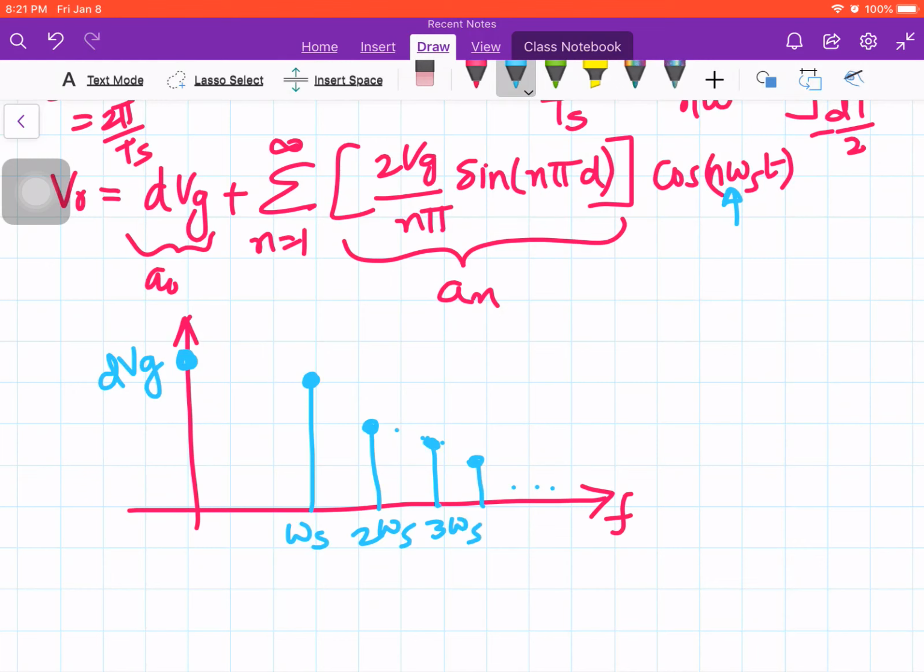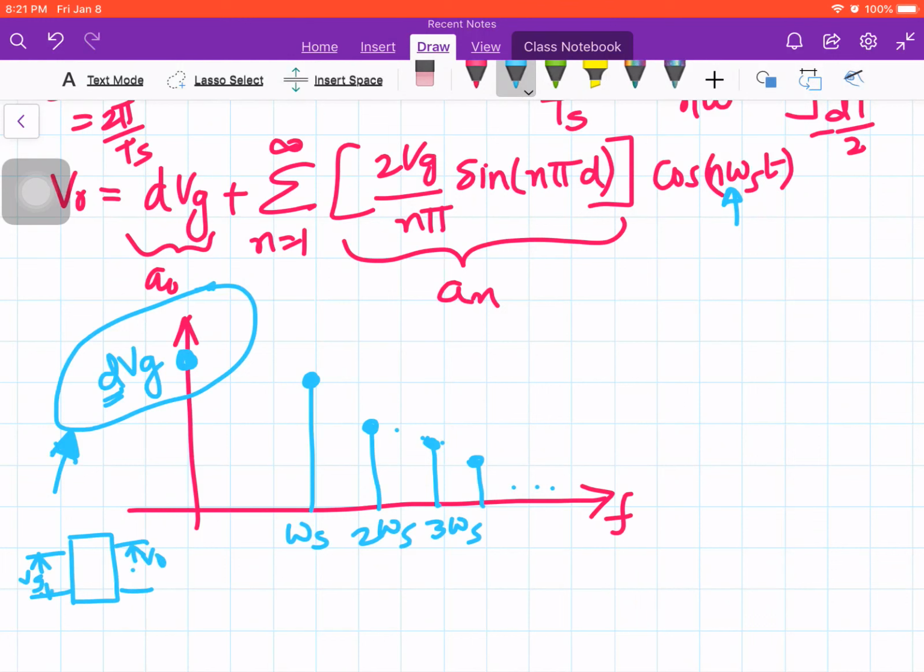The only desirable quantity that we are interested in is this one. Why? Because we are trying to control the output voltage using the parameter D. Usually our objective will be that we have some supply Vg and we want some other voltage Vo which can be controlled based on the application. So this is my switching network here.